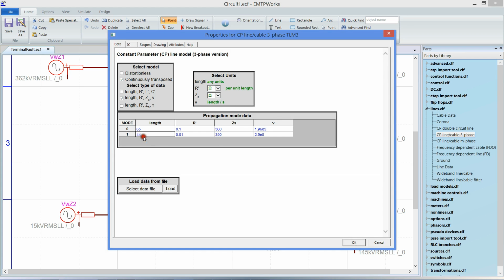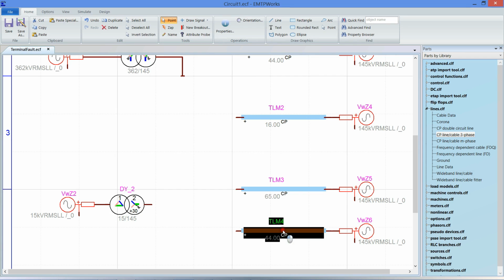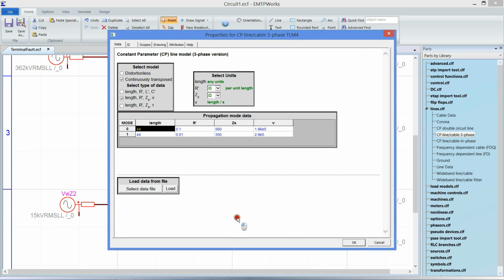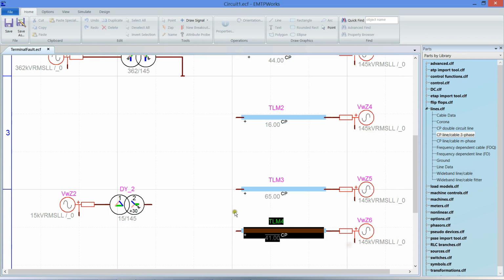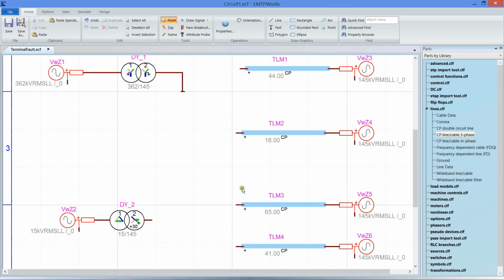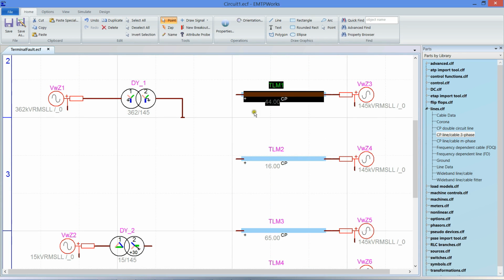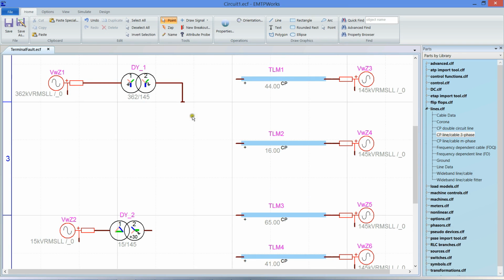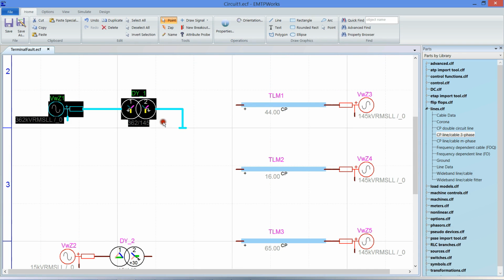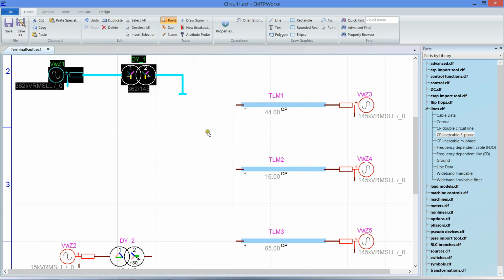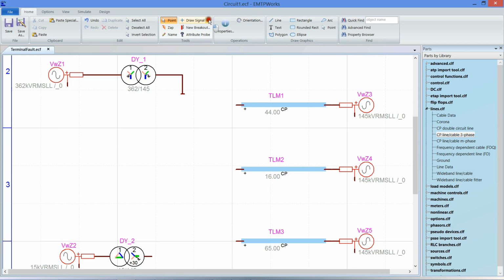Another option is just to start with a typical one, for example 1 microsecond for such a study, and look at the waveform to see if the results are not segmented too much. But it's always better to know before running the simulation what you expect to have. And it's actually why this guide, from which we reproduced this example, is very good, because it gives a way to find out before running the simulation what's going to happen.